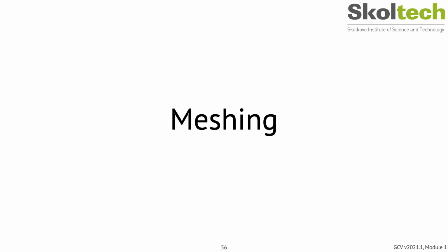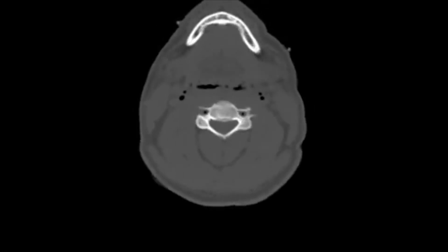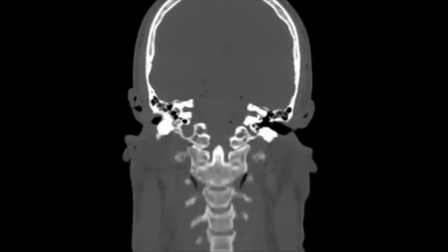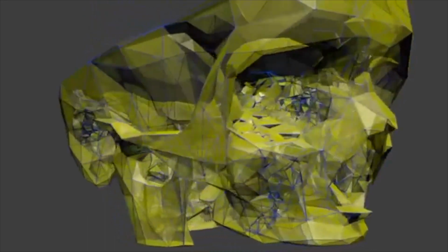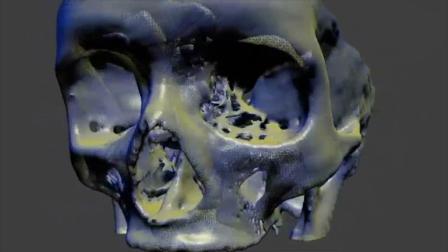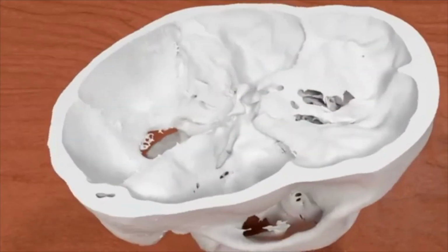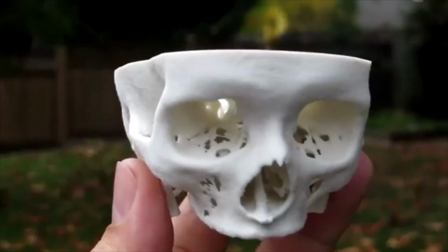Having obtained a zero-level set of an implicit surface, or having fitted the implicit surface by estimating the SDF, our goal will be now to actually extract the discretized representation of the surface for further use, for example within a computer graphics or other application. This process is referred to as meshing. The conversion from an implicit or volumetric representation to a triangular mesh, the so-called isosurface extraction, occurs, for example, in constructive solid geometry modeling, and in medical applications, for example, to extract the skull surface from a computed tomography head scan. The de facto standard algorithm for isosurface extraction is the Marching Cubes algorithm by Lorensen and Cline from as early as 1987.